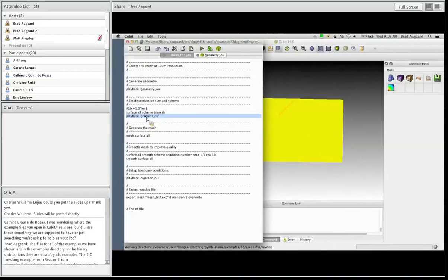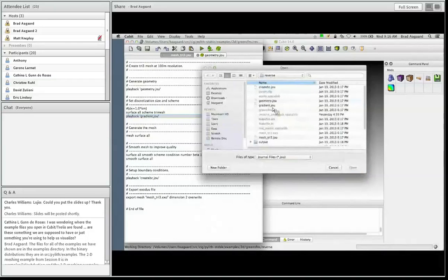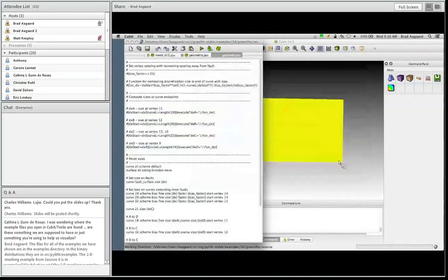What this is going to do is grade the mesh away from the fault. In Green's functions, we're specifying a unit impulse right at the fault, so we need relatively high resolution to resolve that unit impulse right around the fault. Our mesh resolution will actually dictate the resolution of our impulses. So we'll have a 1 kilometer length scale for our impulses on the fault.